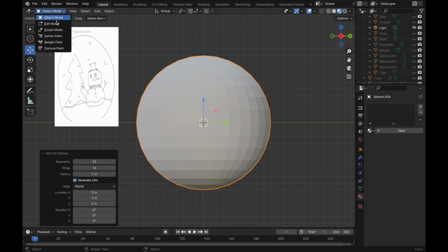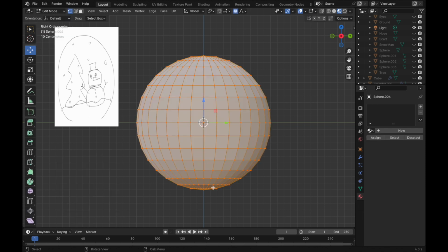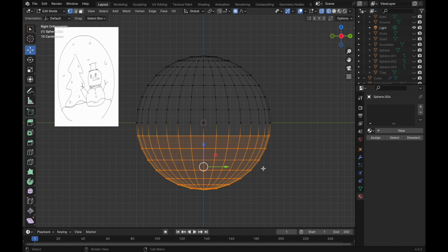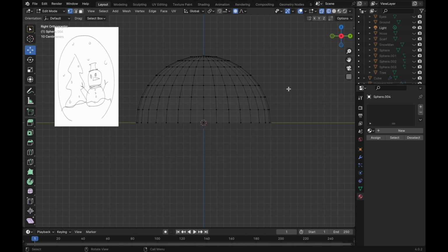Click on the Object mode, select Edit mode. Draw a rectangle area around all vertices below the Y-axis. Oh, let's go to the wireframe mode. This is like an X-ray mode of the solid mesh, so that the vertices behind will not be left out when selecting. Redraw a rectangle to select all the vertices. You may have noticed that the orange color representing the selection became more prominent, which implies that all the vertices are selected. Press X and select vertices to delete these vertices.